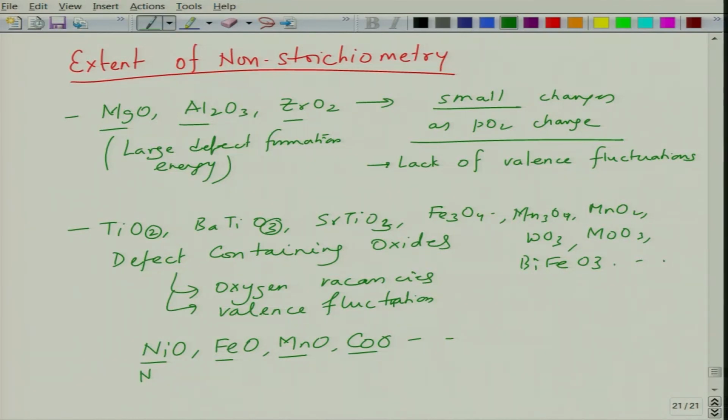So, they can again have a non-stoichiometry of about 0.05%. 0.05% is very large. Okay, it sounds a small number, but when you have about 20 something atoms in a system, 0.05% is a very large number. Here we are talking about stoichiometries of the order of a few ppm, and a few ppm non-stoichiometry is good enough to give you large defect concentration.